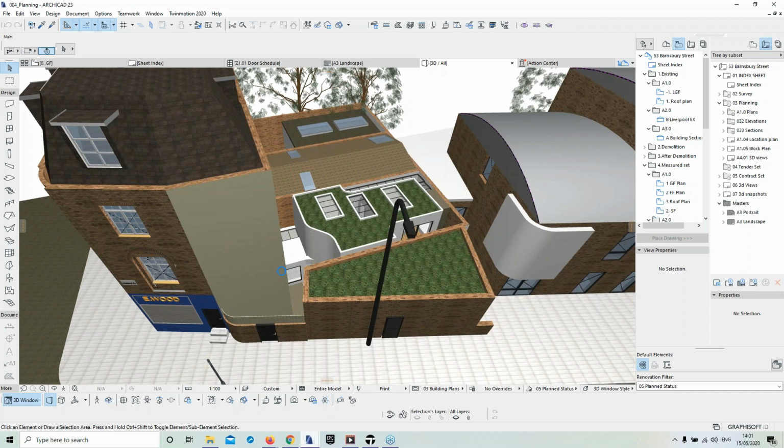So we have various visualization tools within ARCHICAD that we use in different stages. We have the main, which is the 3D model you see on the screen. We have the 3D documents, which is sort of a tool that you can have 2D and 3D information together. We have the BIMX models. We have the internal Cinerender rendering engine. And lately, after the agreement between Epic Games and ARCHICAD, we have the Twinmotion real-time render engine, where I will demonstrate in the end how it sort of surpasses other methods, and it's very helpful at the early stages to